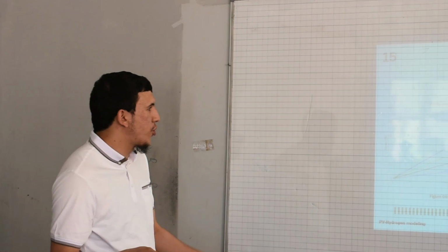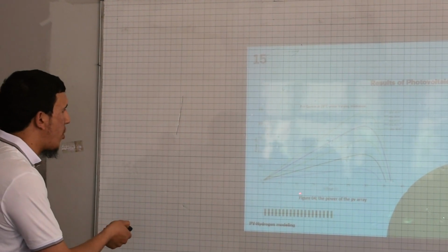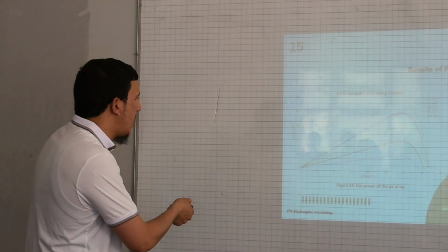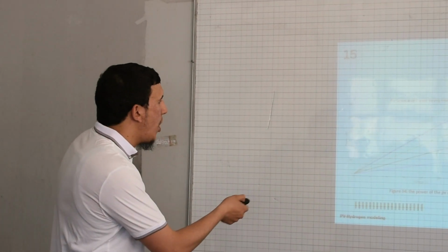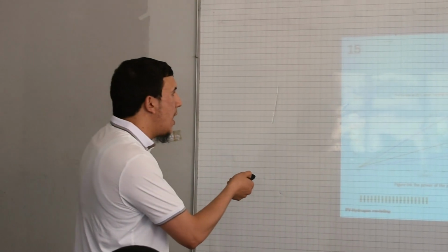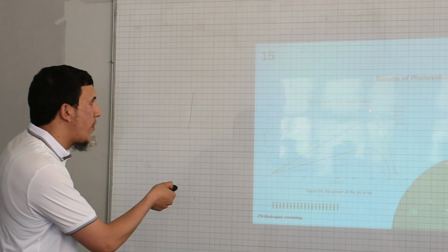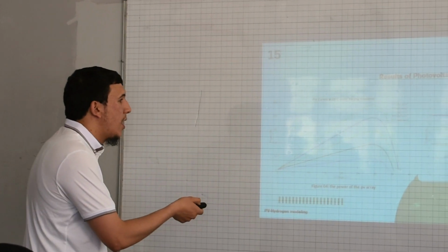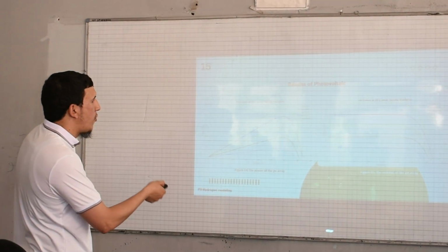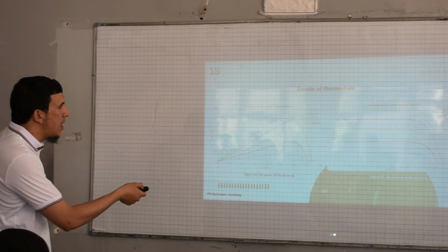The results of the photovoltaic in the mathematical modeling. First, we have our power by voltage. We see here that when the solar irradiance is going up, the power is going up. Here is the maximum power point that we focused on in our MPPT algorithm. We see the same for the current. Like the current by voltage, the current is also related to the sun irradiance.